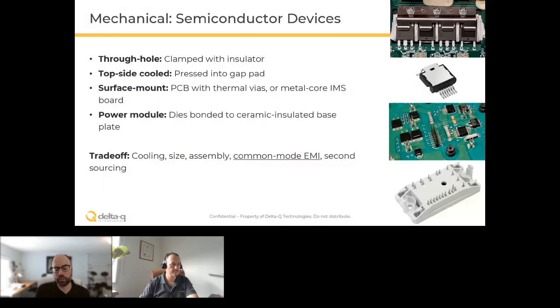So you may have to add stiffening or have a lot of mounting screws through that board, each of which will have a certain keep out area, and that causes the size of the circuit board to kind of blow up. So I would say yes, but there are definitely trade-offs here, but it's something that we are looking at closely.